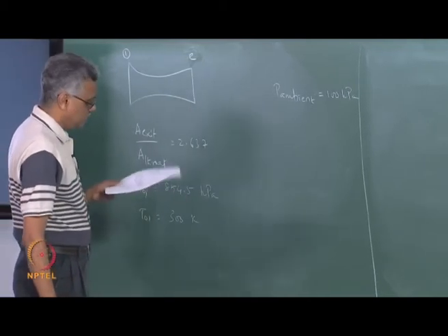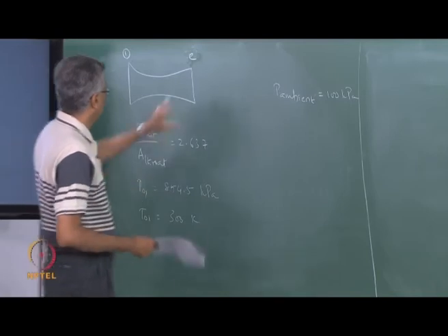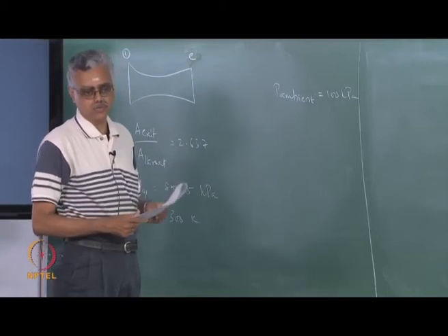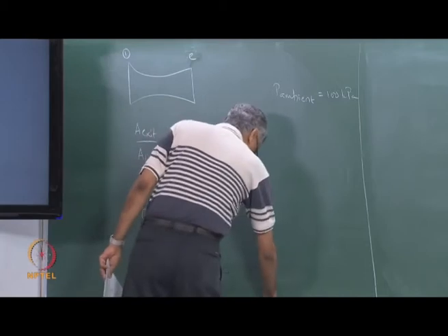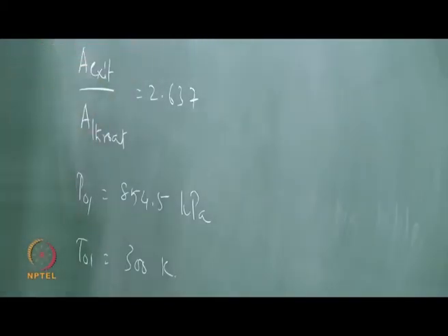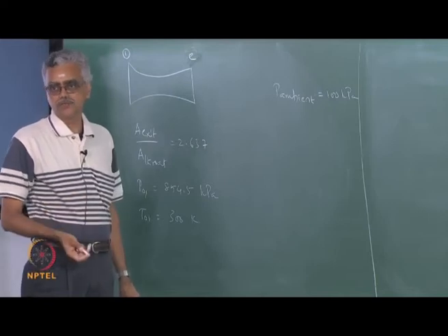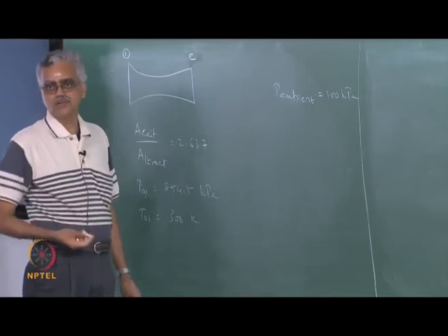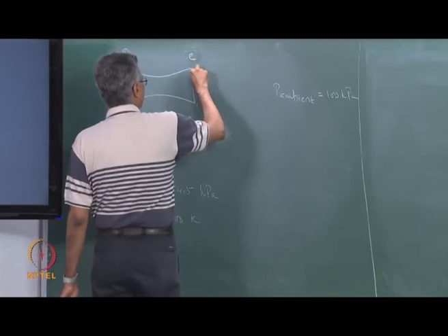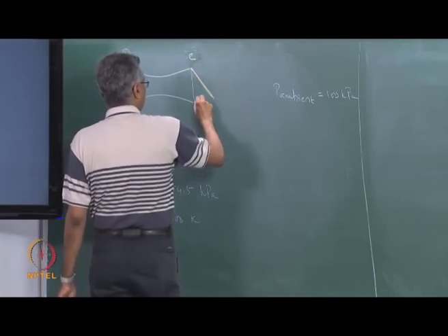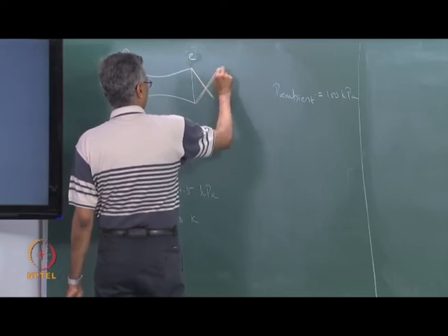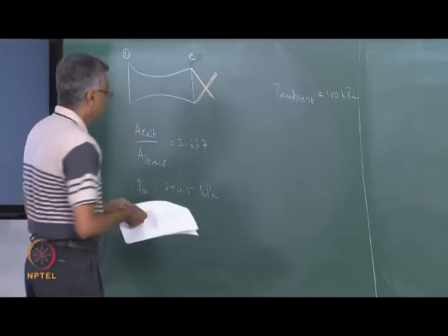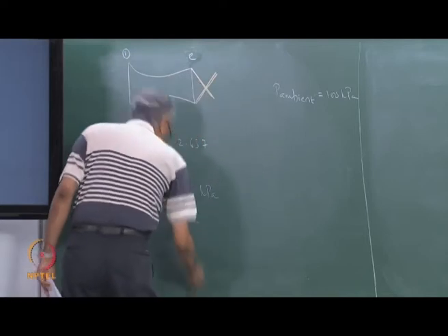We are asked to determine the flow properties at the exit and also the angle made by the edge of the jet with the horizontal. Okay. So, let me sketch the situation that is given in the problem. You know that when it is overexpanded, that means that the flow has to be compressed after it comes out. So, that means we trigger oblique shock waves from the lip of the nozzle, and the jet is then deflected like this.